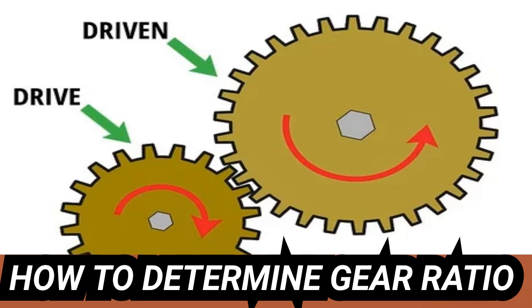5. More than 2 gears. 1. Start with a gear train of more than 2 gears. As its name suggests, a gear train can also be made from a long sequence of gears, not just a single driver gear and a single driven gear. In these cases, the first gear remains the driver gear, the last gear remains the driven gear, and the ones in the middle become idler gears. These are often used to change the direction of rotation or to connect two gears when direct gearing would make them unwieldy or not readily available.